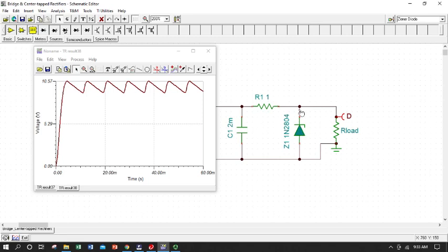So if we connect our Zener across the circuit here and take a look at this node up at the top, we know that whatever the reverse breakdown voltage is that the Zener is rated for, that Zener will open and conduct with negligible resistance once that voltage is exceeded at that point.